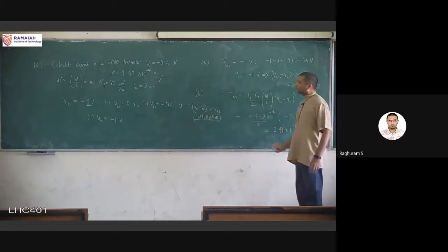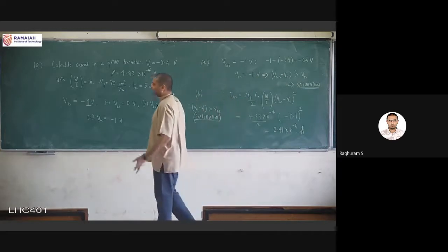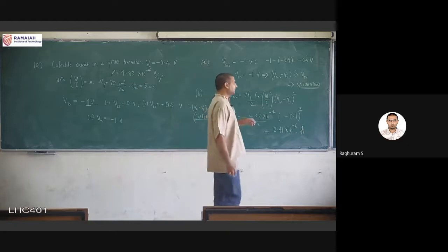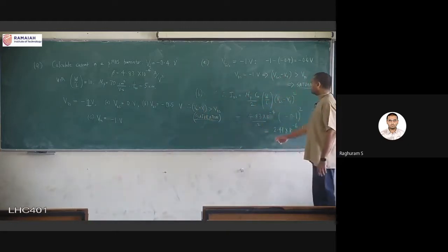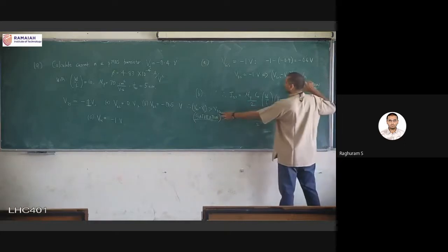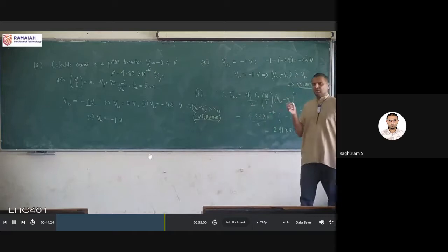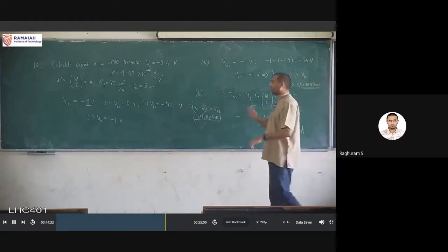Okay, so again, if you just compare VGS minus VT with VDS, we see that it is still lesser. That is, VGS minus VT is greater than VDS, which means it continues to be in the same conditions here and here. Even though the value of VGS has changed, it is still not in linear mode. And to be in linear mode, it will have to go even higher. So if you want, you can try this later.